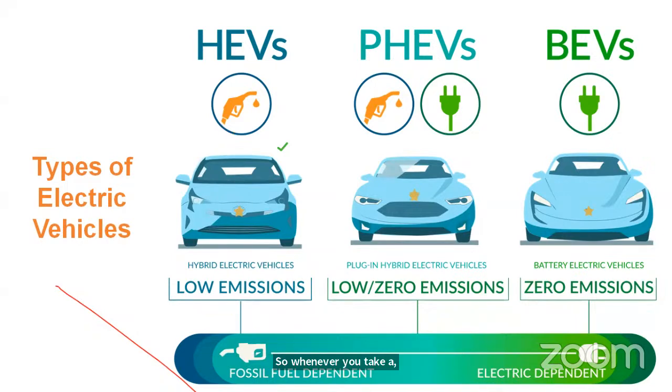We have some power electronics, and that power electronics can switch the motor phase so that it converts from motor to generator. When you apply the brake, the brake supplies the rotational force to the generator, and that generator generates some electricity, and that electricity is used to charge your battery pack. That is the way a hybrid electric vehicle works, and the way its battery gets charged.